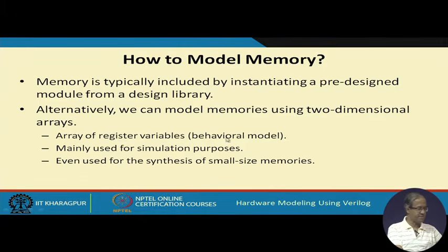Of course, this is a behavioral model and we shall be looking into this, and this is quite useful for simulation purposes to check whether the rest of your design is correct or not. And also for memories which are relatively smaller in size, there also you can use this kind of behavioral model. But for larger memories, as I said, you have to take some module from a library, a design library.